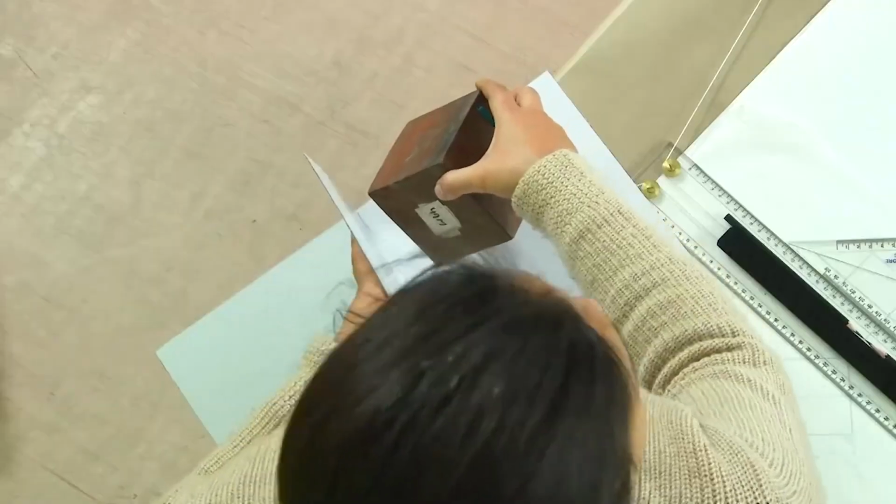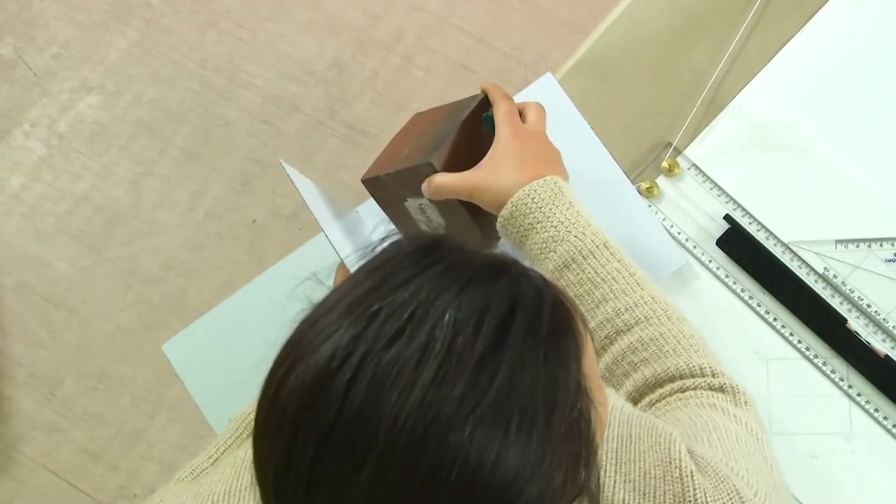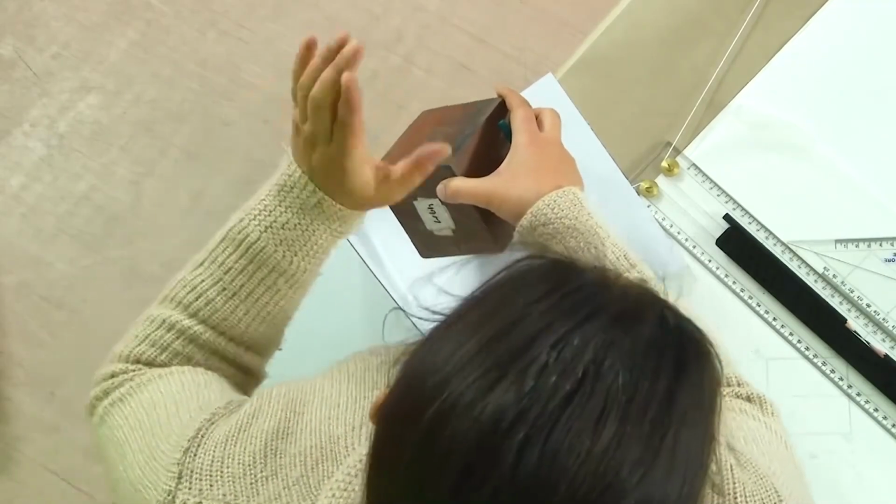We have to mainly concern ourselves with, or start with, the axis. So, what happens when we move the axis, assuming that the axis is only from the bottom of the base to the top of the base of this cube? When you incline it 30 degrees, we assume that this line, which is the axis, is inclined at 30 degrees. So, in the front elevation, we will be seeing the axis inclined at 30 degrees or whatever angle to HP. And the rest of the things will remain as they were if it was kept like this, perpendicular to HP.